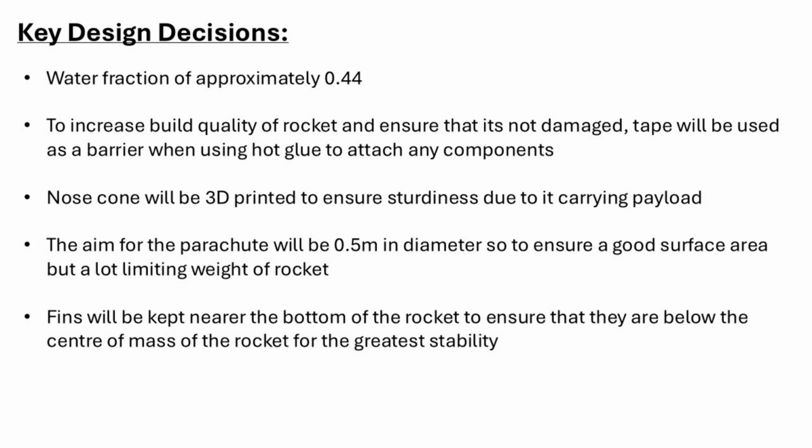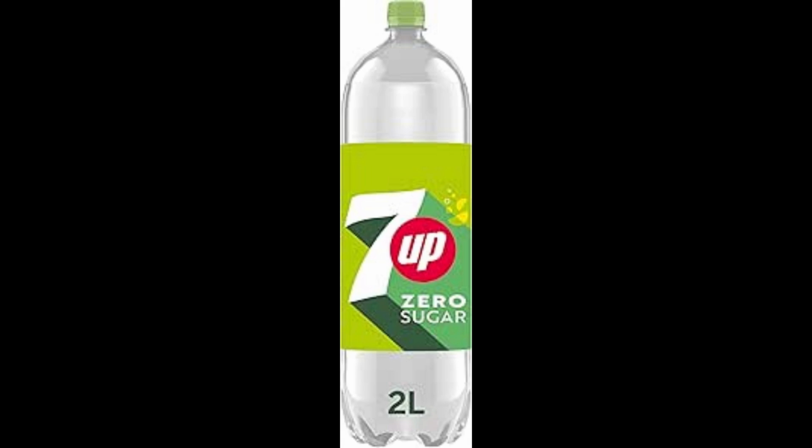Finally, we decided that the fins should be at the back for greater stability. We used a fizzy drink bottle, which is made from a more durable plastic than what a normal drink bottle would have been made from, which will ensure us that it won't explode while we pressurize it to 8 bar.